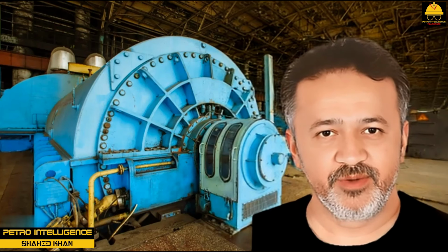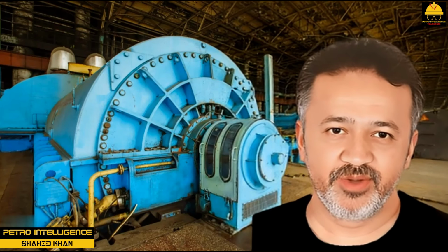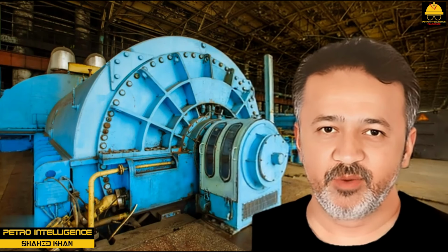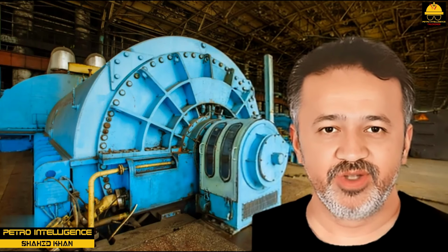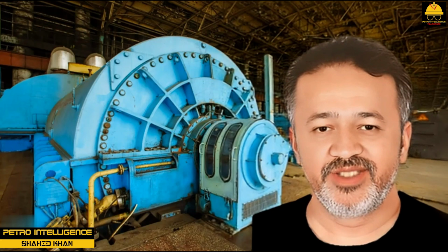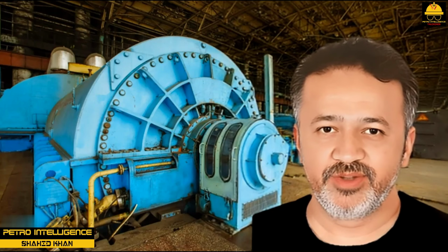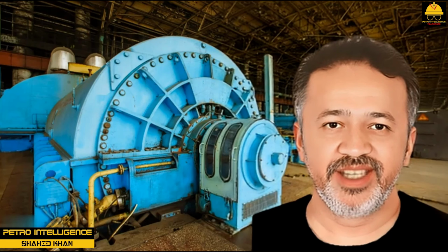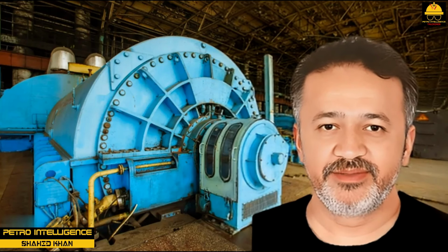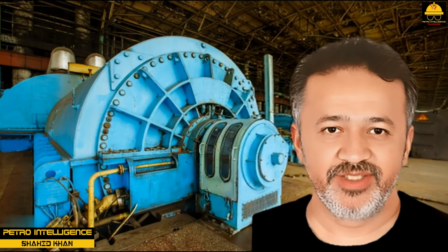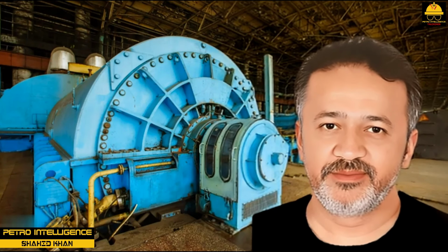A gas turbine uses high-pressure combustion to turn a series of turbine wheels to provide rotational energy to a driven device in the same way a steam turbine uses steam to turn the rotor. The gas turbine system mixes compressed air with fuel in a combustion chamber. A spark plug ignites the mixture, which is directed into the suction side of the gas turbine. The hot combustion gases rush into the gas turbine, causing the turbine wheels to turn.